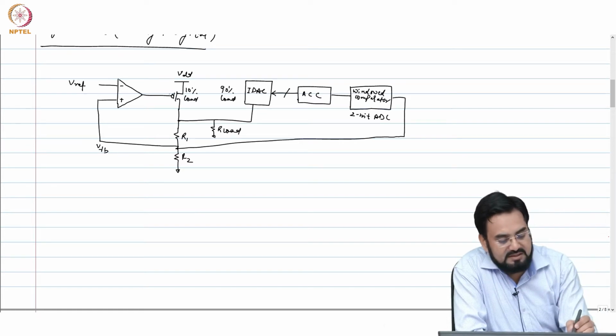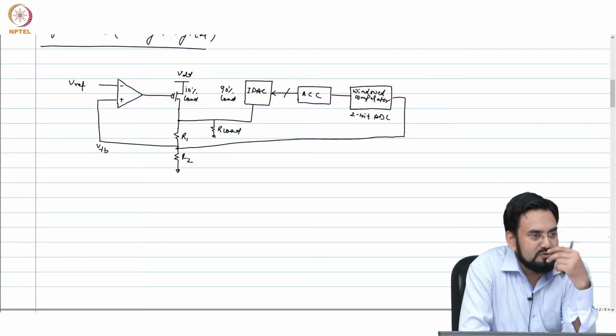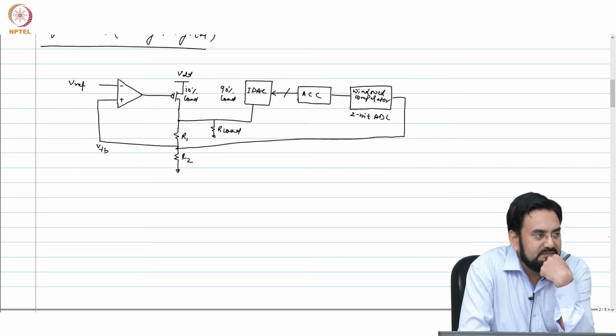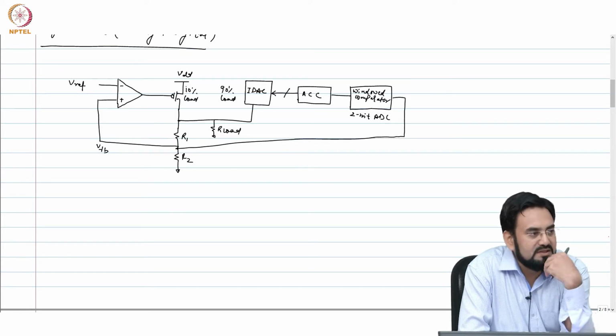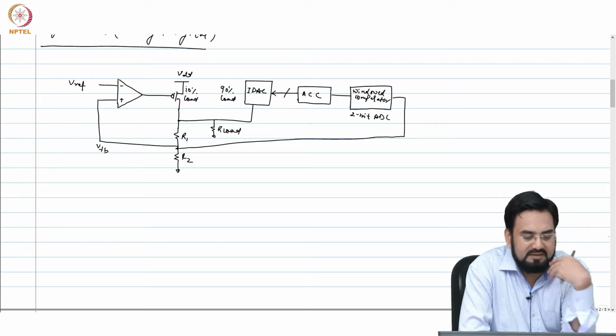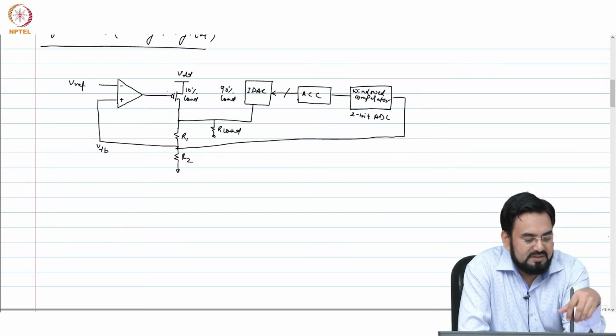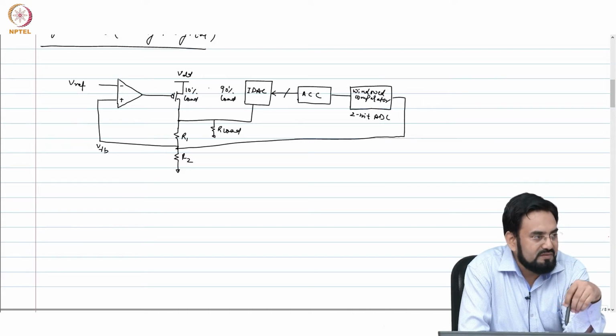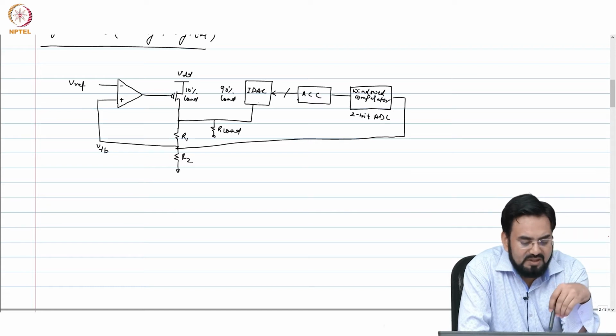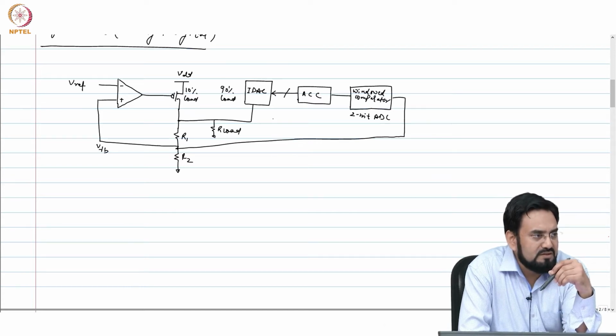So, you can sense this analog current and you know this analog cannot take more than 1 milliamp, that is what you have designed for. So, whenever current goes above 1 milliamp, you just activate your DAC, okay. So, you keep increasing that. So, what will happen, your this current will start reducing. So, let us say the LSB you have turned on, okay.